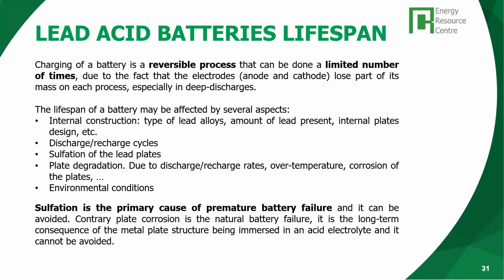That is the phenomenon we know as sulfation. That is the great danger of lead acid batteries: those sulfate ions cannot be dissolved again in the electrolyte.